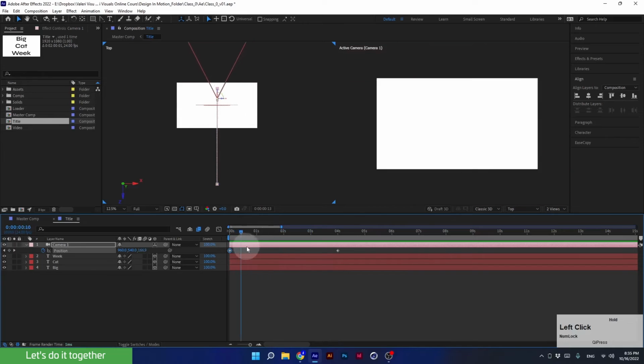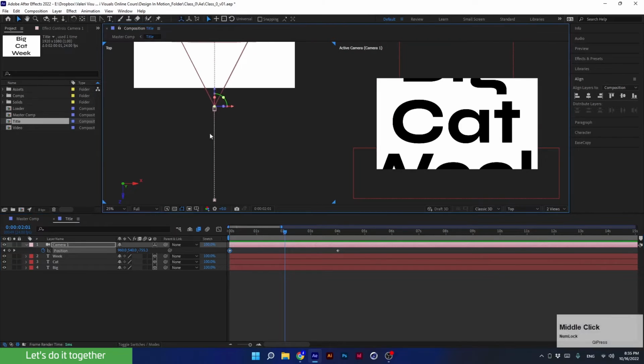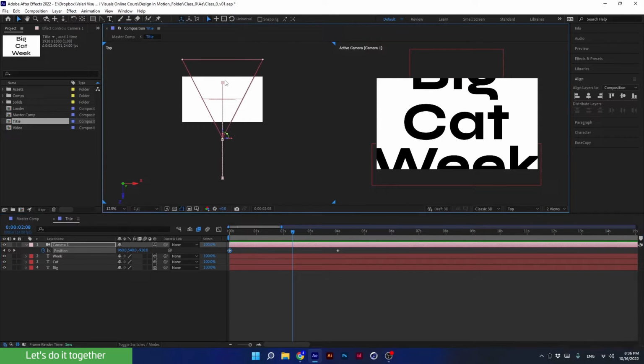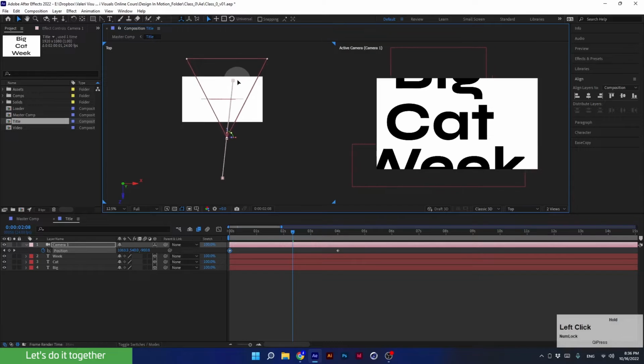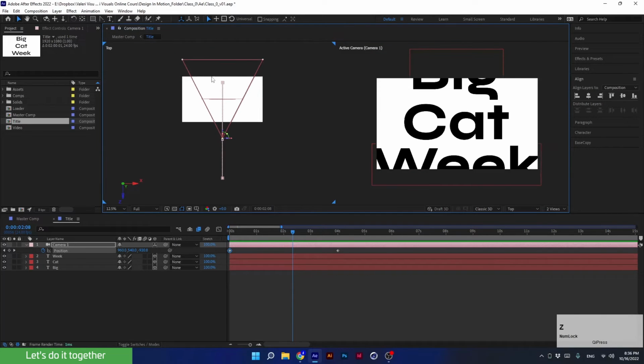As you can see, because we animated the position parameter, a path was created. Just like it was created for a shape created by a pen tool, and just like it was created for every layer with a position animation. Like any layer in After Effects, the camera is also just a layer. So when we animated the position parameter, a path was created. And like any path in After Effects, we can grab a certain point and move anywhere we decide. I will press Ctrl Z.